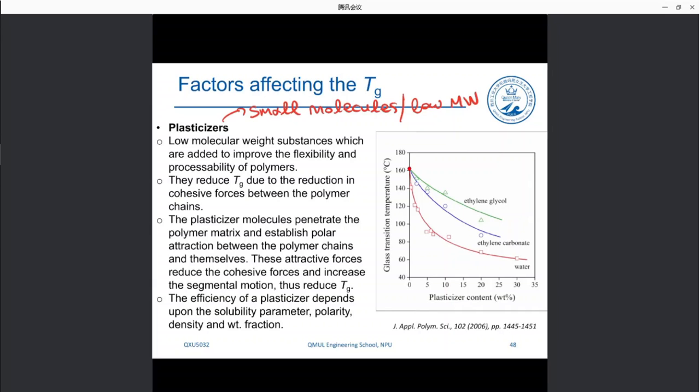These are small molecules that get between the polymer chains and make them space from each other, okay? So you have the polymer chains like that, and you use a plasticizer here, another plasticizer here, and you open up the distance between the polymer chains, okay? By opening this distance between the polymer chains, what happens? We increase the free volume.